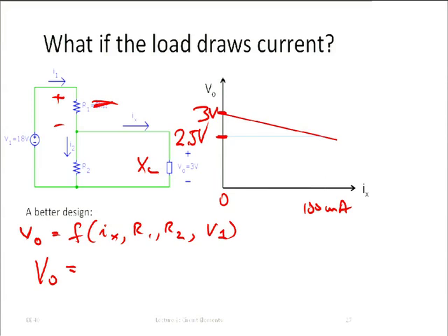Well, let's try an equation. What else do we know? Well, we actually know what V1 is. The voltage V out, which is the voltage here also, is going to be equal to the voltage V1 minus the voltage, let's call this VR1 or so. Again, we can give it a name. So what is that voltage? Well, it's going to be equal to the current that's flowing there, I1, I have that at the top, times the value of the resistor R1. Okay? That's certainly an okay equation, right?